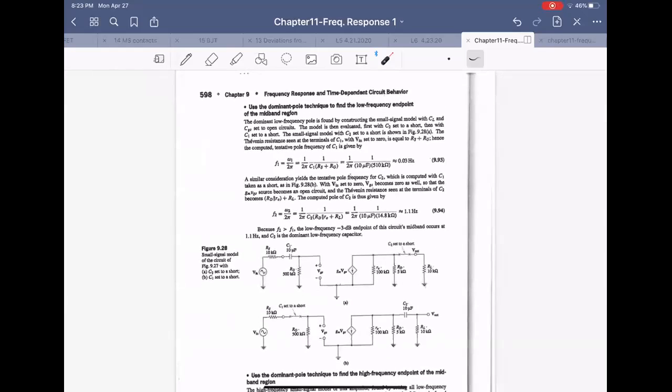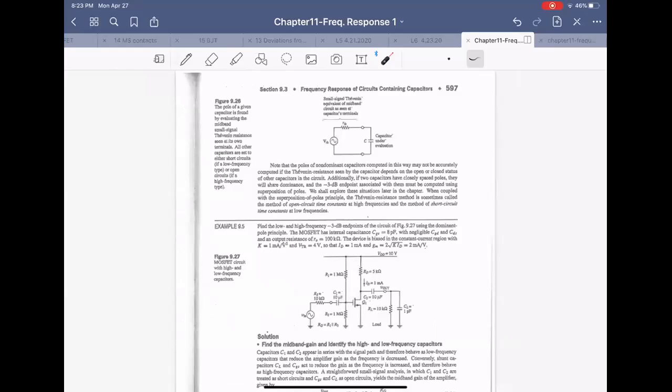Okay, let's find. We don't need to solve this problem again, okay? Just how we can get this F1 or F2, FL1, FL2. Let's say this FL1, this FL2, because at low frequency this bothers, right? Impedance is so high, a lot of attenuation by C1, a lot of attenuation by C2, will have very small output voltage. And at low frequency, we have to consider C1 and C2 like this.